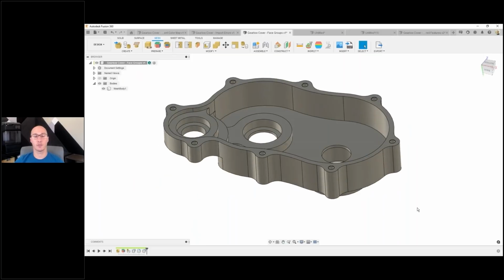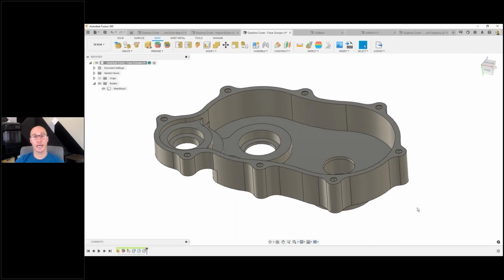This is all possible because Fusion 360 has a direct editing or direct modeling kernel built right into it, and also Fusion 360 has the ability to convert that mesh into a nice, clean solid. You combine those two things together, and now I have STL file editing made easy. So you can take models from Thingiverse or from your engineering department or your reverse engineering department and be able to make changes to them very quickly and easily.